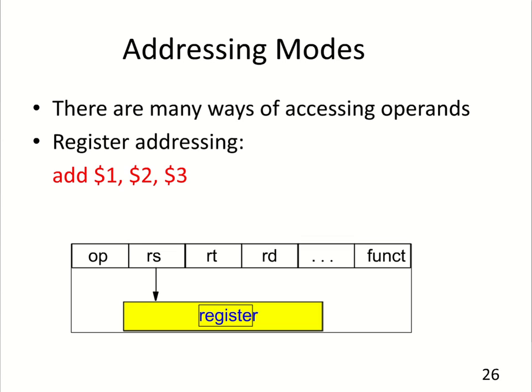We'll close this lecture out by introducing the concept of addressing modes. Addressing modes are an important attribute of an instruction set architecture because they are essentially the way that the instructions can specify the operands that are needed for whatever operation is being performed. And there are many different possible addressing modes. MIPS only supports a small handful. Other instruction sets support many more. We'll see a few examples of those in the next lecture.